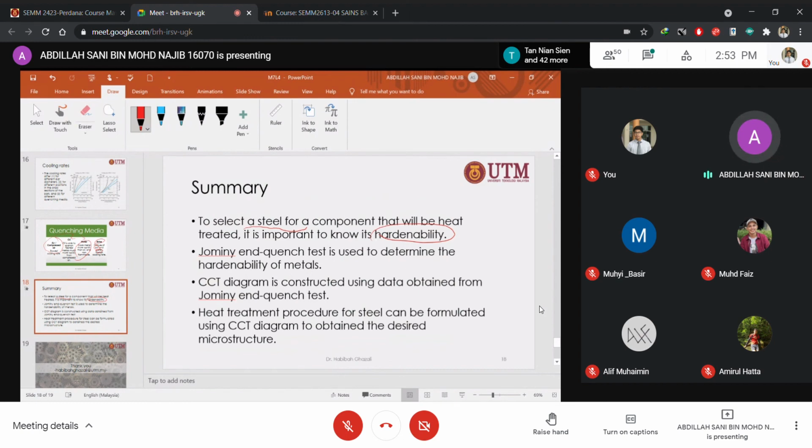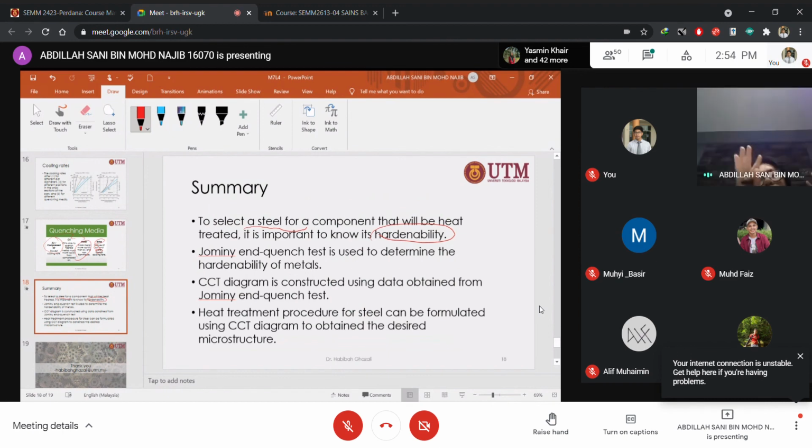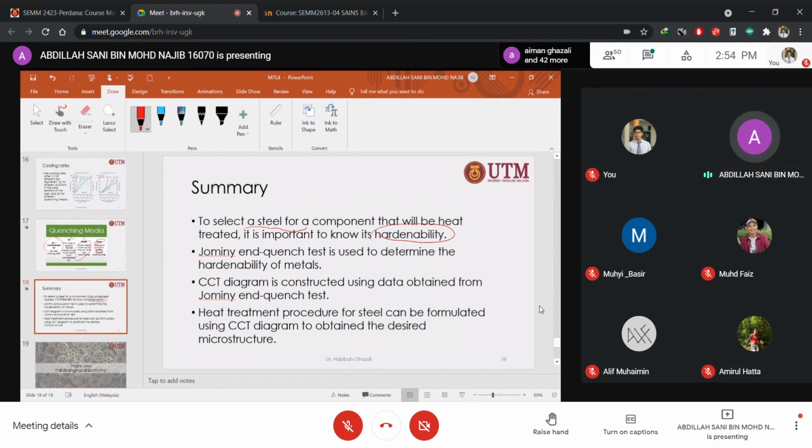The material may come in the form of a slab. When you deform it or do the heat treatment, you wouldn't want to assume that it's the same as the material coming in. The microstructure will be very different. Even inside the same material, each area at the surface is different. You go deeper, it is different. How about the core? It will be very different.